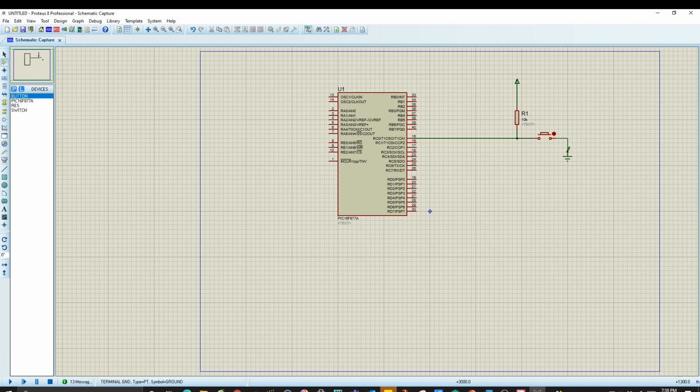To the ground. So you have to imagine the rules for electronics, or electric. If you short this one, then the connection will go to 0 volt. If there's no connection, it will go to 5 volt. So that's why you can measure the output signals here. If you have a multimeter, you can use a multimeter here, DC voltmeter. Right now you want to measure which point? This point to the ground.